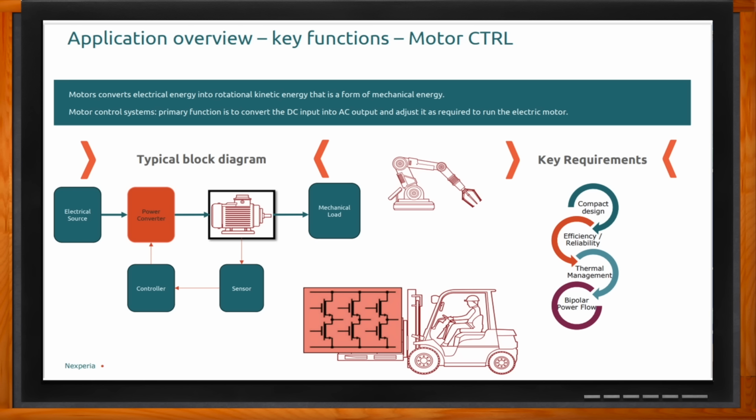The main reason for that is that right now, the MCU and the power converter are separate. So there are wires required to go from that package to the motor. And now, if we can reduce the size, the MCU and the power converter can go right on the back of the motor, sort of plug in directly, and that will not lose any more power. It will be higher efficiency. There's no need for high gauge wires, and it's going to be one unit, just the motor itself. All you have to do is plug it in and connect the motor shaft to your load, and that will work through it.